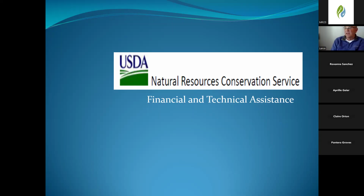Yes, mixed. Okay. So then we're trying to do the best we can to determine how to best apply water based upon the diameter of trees. We do have a chart that we can share with you that was developed by University of California that shows water requirement for avocados based on that tree diameter. And if you've got 3 different types of sprinklers, the recommendation I would make is that you use flow rates that are divisible.